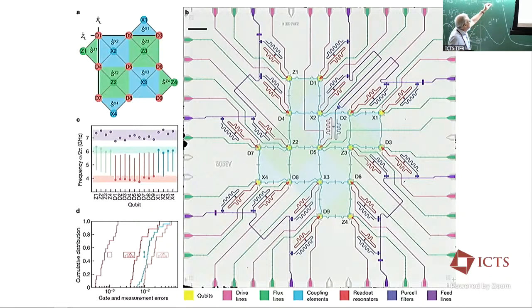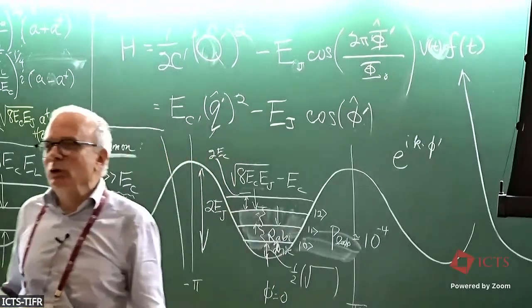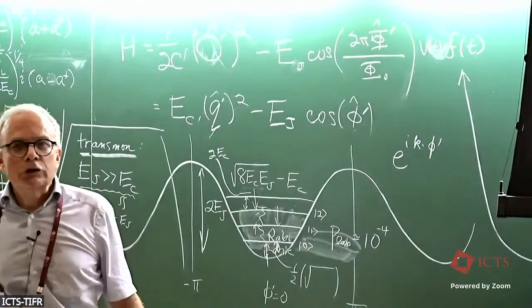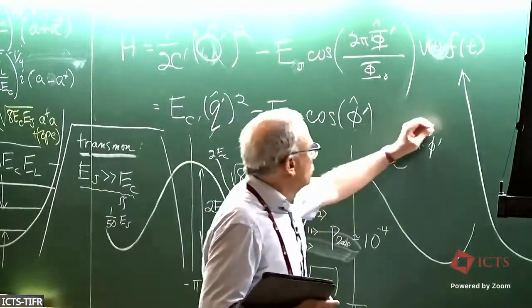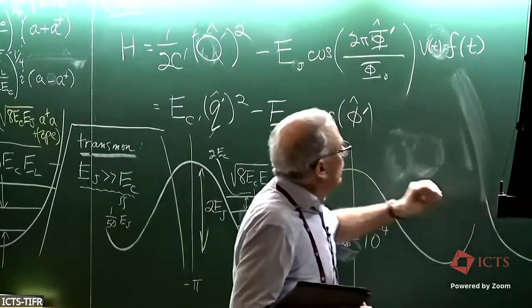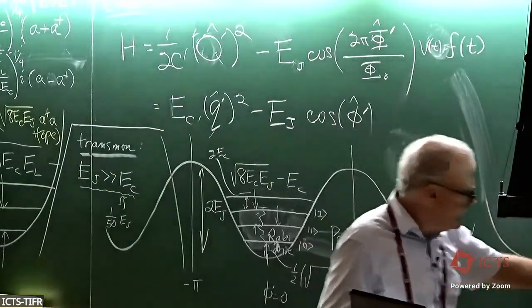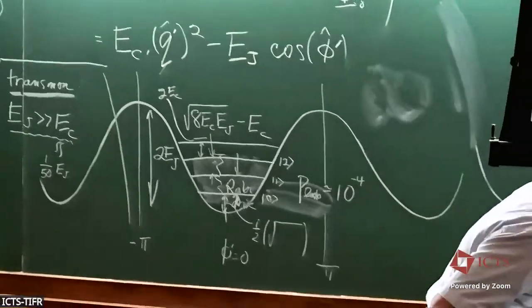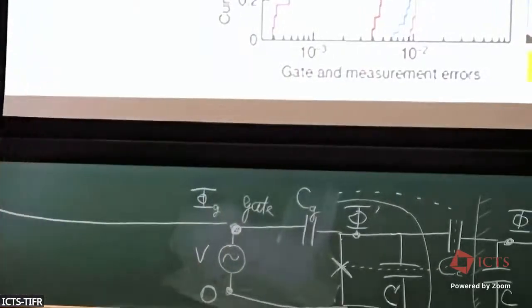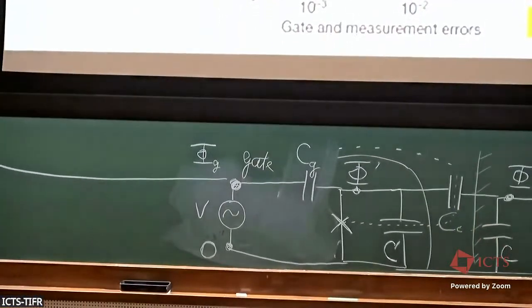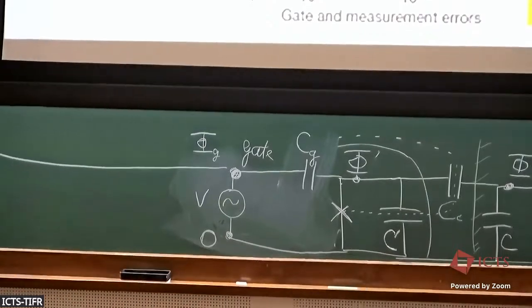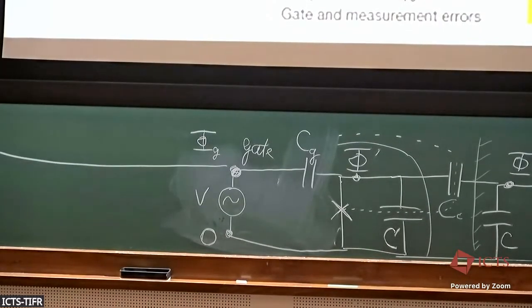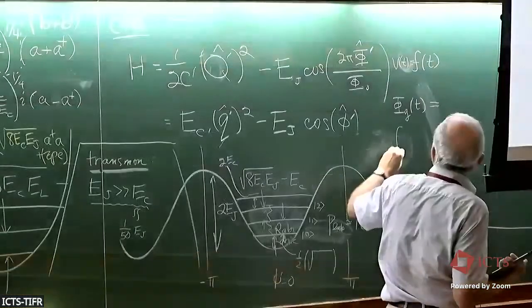So the voltage of time is just some function of t, which for a signal generator is sinusoidal. If it's an AWG, arbitrary waveform generator, it can be almost any function of t respecting certain restrictions. Now, remember, we'd like to say things about phases. So there's a phi g here. This is a new node of this circuit, and it's a phi g. But phi g, observe, I'm doing classical physics again, is just a time integral of V of t.